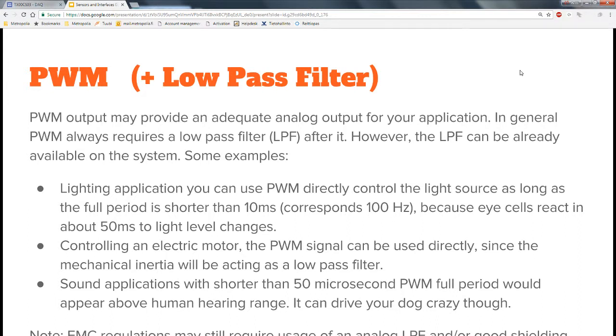But if you are running very high loads, there are some EMC regulations, of course. For example, those paper machines. It's not that straightforward to just say, hey, PWM, then it works. You might actually see some high frequency, high current arcs forming if you just run those as you wish.